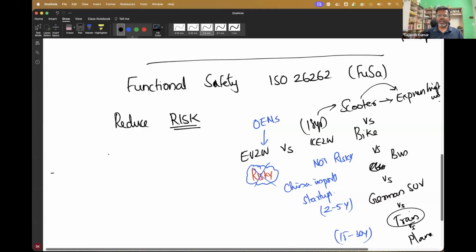How do you basically do that? The definition for risk, at least from a functional safety perspective, they're able to define in a much easier way. They say that the risk is a product of severity. We've already done it, right? Exposure, or how often does it occur, multiplied by, there it was detection, but here it is controllability.